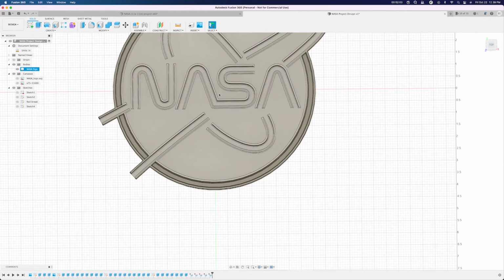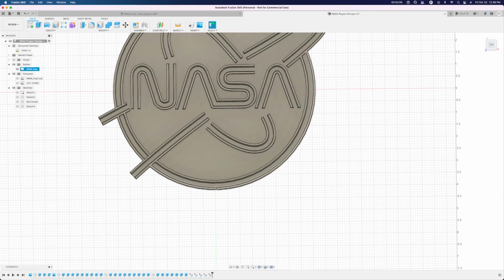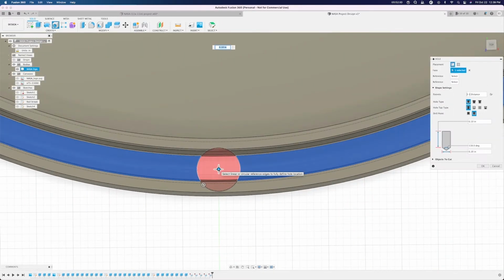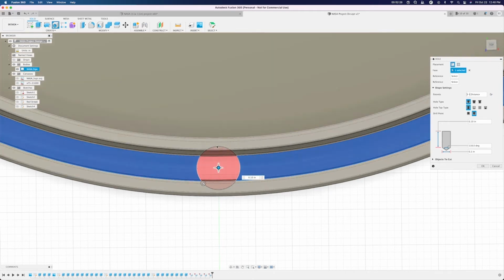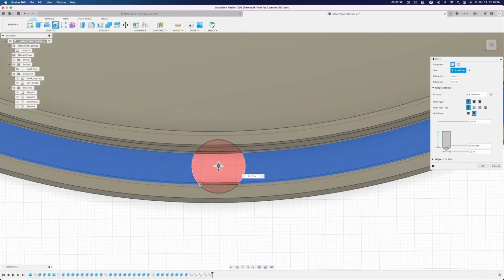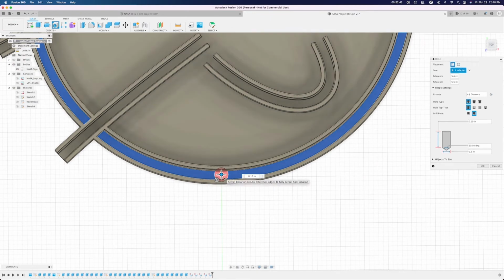Now, of course, we'll actually need a hole that goes to the design itself at the very bottom, as we'll need some sort of outlet that connects to the actual wiring of the neon. So if you're gonna go and click on this hole tool right here at the very top left, click on that, scroll down to the very bottom right here, and just click on the middle right there. And I'm gonna set this to a radius of 0.3, and make sure it's centered in the middle as much as you can. So for example, if you're looking at this little outside line and outside line here, make sure it's centered, because if you have it way over here, when you're printing it, it may not come out the way you intended. But of course, this is your design, and press enter.